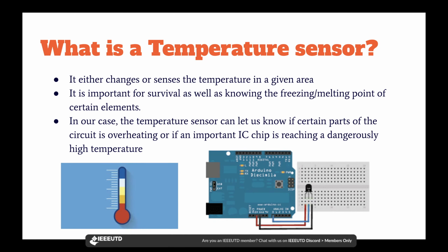A gas sensor detects different types of gases within an environment. A few are methane, carbon monoxide, ethanol, and there's more. The detection is based upon a change in resistance of the sensing material when the gas comes in contact with the material inside of the sensor. Gas sensors are important because they can detect concentrations of certain gases as well as check if they're toxic.